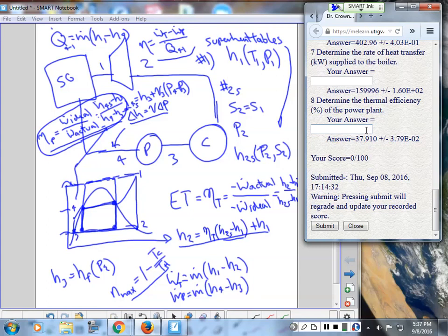Yeah, it depends. So for an ideal gas, delta H equals Cp delta T. That's a good assumption for an ideal gas where the temperature doesn't change a lot. So for the compressor, yes, that could work if there's not a really big temperature difference, or if I'm allowing some tolerance on the answer. But strictly speaking, that's an assumption that's not as accurate. If Cp is a function of temperature, then you're going to have some error introduced there.